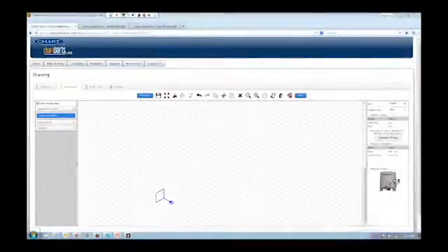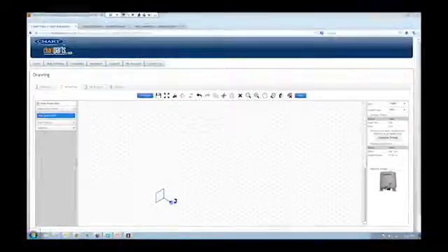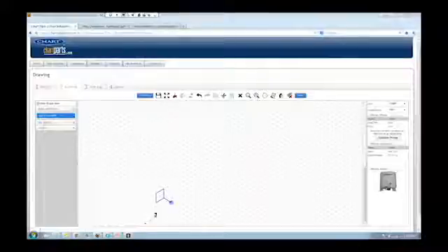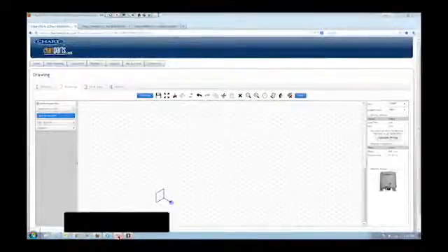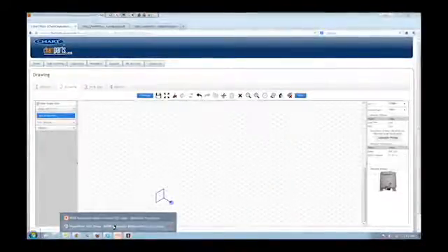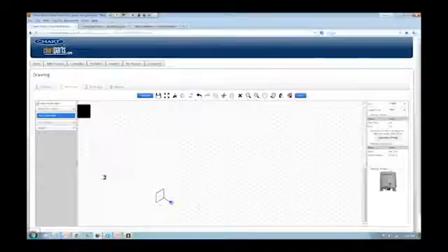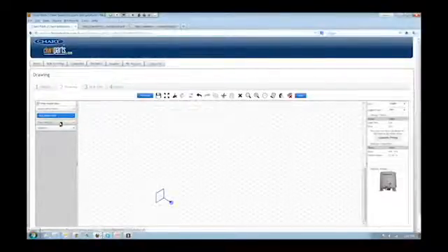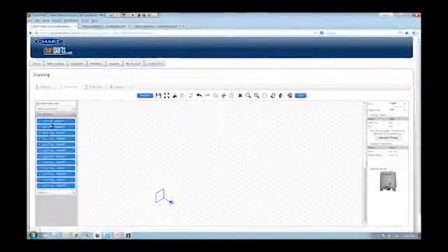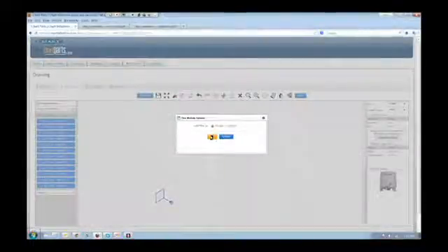Okay, so I just started out here with a bulk tank, a starting point. It's an MPT connection. What I'm trying to do is draw this customer sketch that was submitted. So the first piece that I'm going to be adding here is a flex module, and it's a 6-foot flex module that goes MPT to male bayonet. I'm going to add that as a straight.